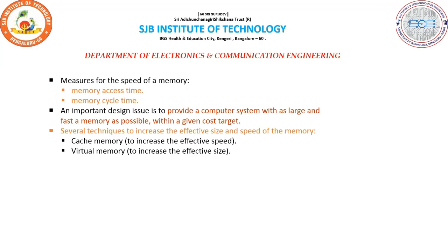The processor writes data into a memory location by loading the address of this location into the memory address register and loading the data into the MDR. It indicates that a write operation is involved by setting the read or write line equal to 0. The R/W bar notation indicates that the write is an active low signal, while R indicates an active high signal. The same signal can be utilized for the two operations, read as well as write. Whenever the signal is active high, it is for the read operation. Whenever this signal is active low, then that is for the write operation.